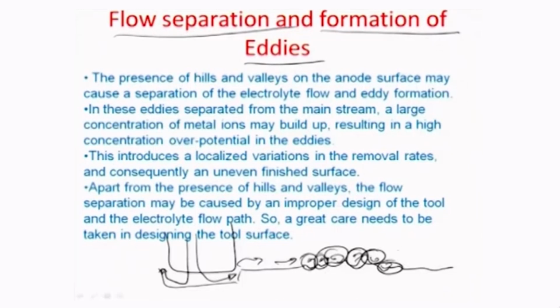There are selective dissolutions because of which there is a lot of this cornering effect, chamfering effect, which is present at various points here. Okay. So, these local circulations are a cause for the debris particles which come out of this zone to keep circulating here without going further. Okay. And that may change the local conductivity, because precipitates are again one of the responsible causes for change of the conductivity of the medium electrolyte.